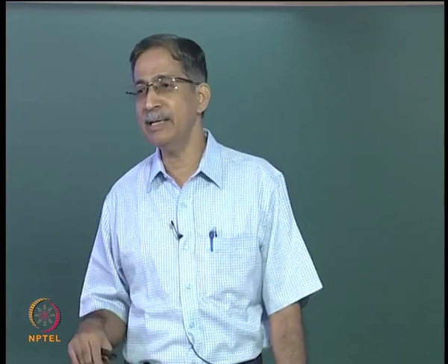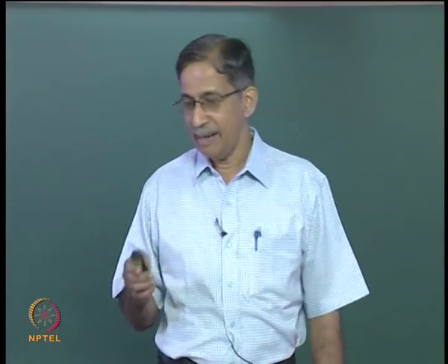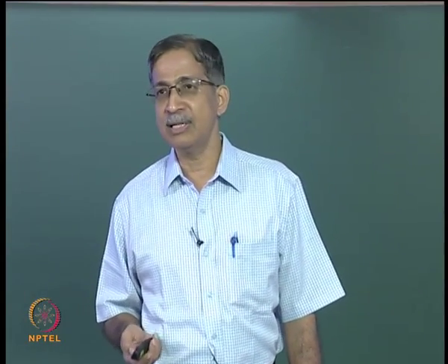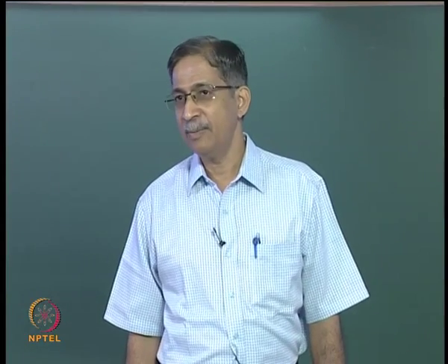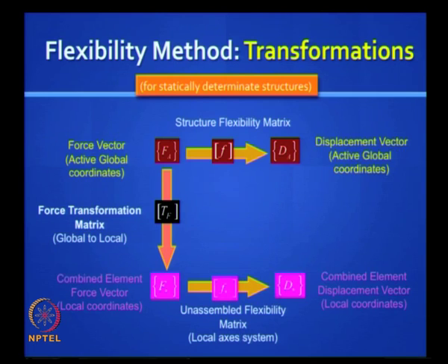So that is shown here, FA and DA, and the basic force transformation is the TF matrix, which really tells you that if you give the loads on the structure, you can directly get the relevant internal forces at the element level by doing that TF transformation.